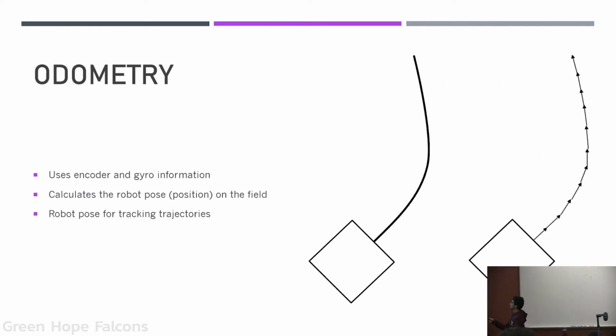And we can calculate the delta x and the delta y along each small vector, and then we can add all of those changes in order to get our robot's position. So that's what the classes are doing under the hood. Now, if you didn't have WPILib, you would have to implement all of this math by yourself. It's a lot of trigonometry. But because you have WPILib, you don't need to know how any of the math works. All you have to do is create a class and call that class.